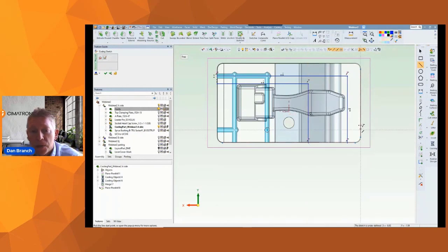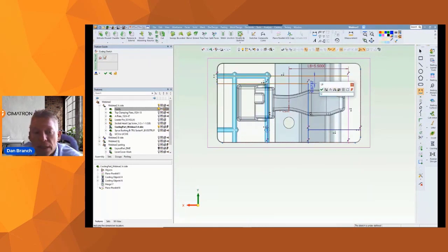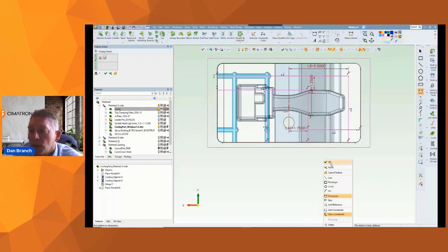Keeping in mind, of course, that drilled lines do have to start from one side of the block. And then I'm probably going to add some nominal dimensions on the lines of this new circuit too. Having a dimension means I can parametrically edit the position of a water line later on if it needs to move, which of course they often do.